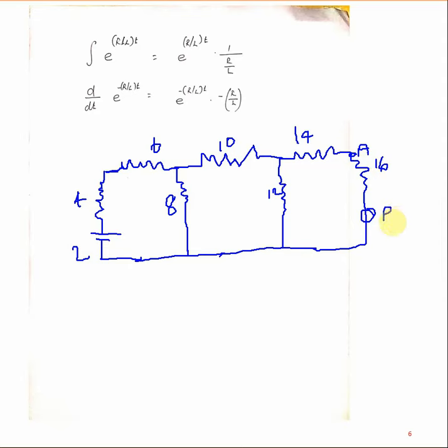With this circuit, you will verify Thevenin's theorem using MATLAB. What is step number one? The load: where is the load point? Remove the load point, and across that you connect the voltmeter. So for step one, I will redraw the diagram for your understanding.